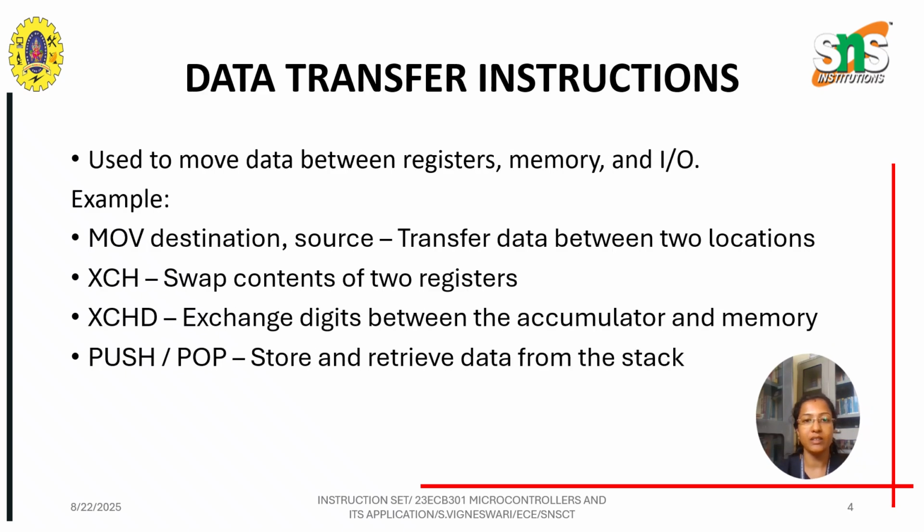First comes the data transfer instruction. This instruction instructs the microcontroller to perform a specific task such as moving the data contents between the memories, registers and input-output devices. For example, MOV moves the content from the source to the destination, and XCH is exchange, which swaps the content between two registers.